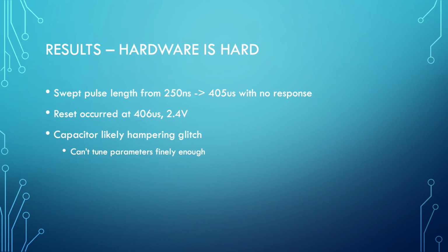The search was complicated by the fact that we're controlling two parameters, pulse length and voltage. The Analog Discovery 2 board has a voltage resolution down to millivolts, but this test is operating closer to the maximum output of 5 volts, and therefore fine adjustments might be more challenging for the board.